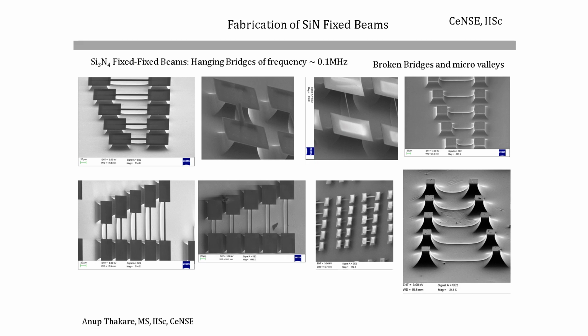Of different dimensions. So this was taken through silicon nitride chemical vapor deposition, followed by patterning with our design. We have made this design and written it with UV lithography, followed by a set of etching for different exposure times, different recipes, and then this has to be validated all the time.